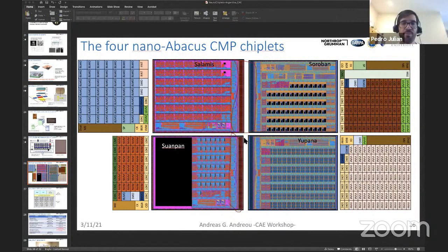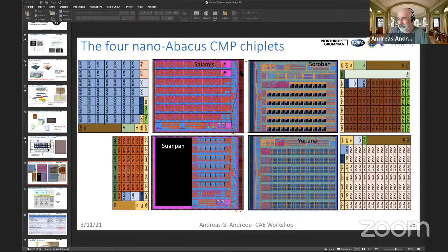Anyway. Makes sense. Yeah, you have SerDes on all the boards. This is not SerDes. This is parallel ports, but they still need to be calibrated. They're not SerDes, and they're not parallel. There are 96 ports here, but each port serializes the data about 10 bits. So it is a serial interface, but it's not SerDes. It's low voltage. Yeah, it's just a standard. That's how they designed the interface.